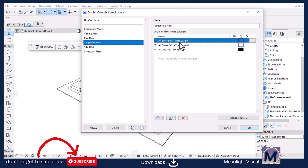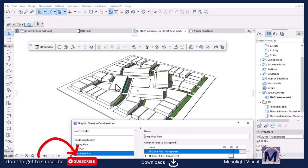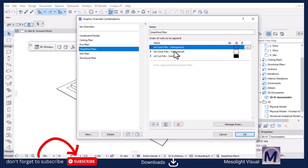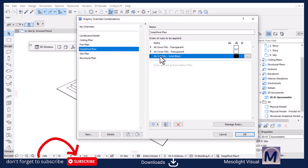Okay, so we're not going to start by creating a new one, we're going to modify on top of it. I think this will help you also to understand how this works. I know it's one of the complex exercises to do in ArchiCAD, but trust me, I'm going to do my best to explain and demonstrate how this graphic override tool works. In this case, we want to differentiate or create a contrast between the residential and commercial plots. So let's see how we can do that. We're going to edit here because this is the main foundation of the rules. So I'm going to click here on edit the rule.